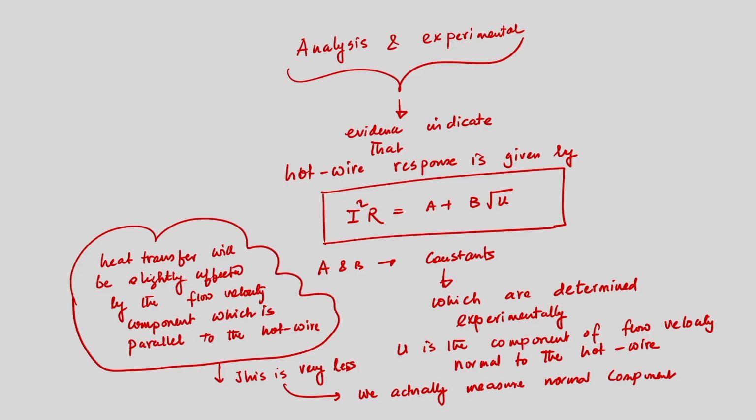Normally it adopts two methods, either hot wire or hot film. Hot wire has a diameter about 1/10 of a human hair, and hot film is a metal film on a glass substrate or other material. And we have schematically depicted the geometrical structure of the probe and the characteristic dimensions.